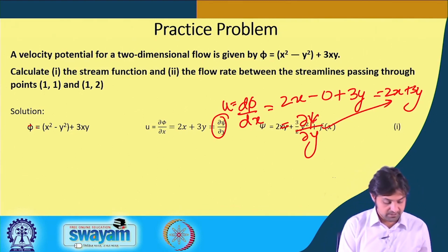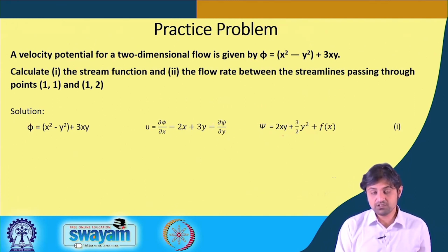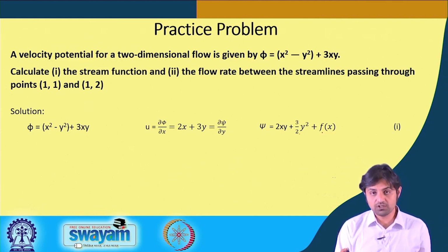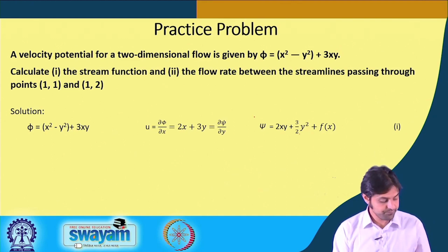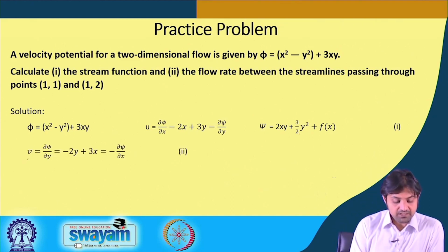So psi can be integrated to 2xy plus 3 by 2 y square, a very simple integration with respect to y, plus not a constant but f of x, because that is a function of x. Similarly, v is given as minus del phi by del y.